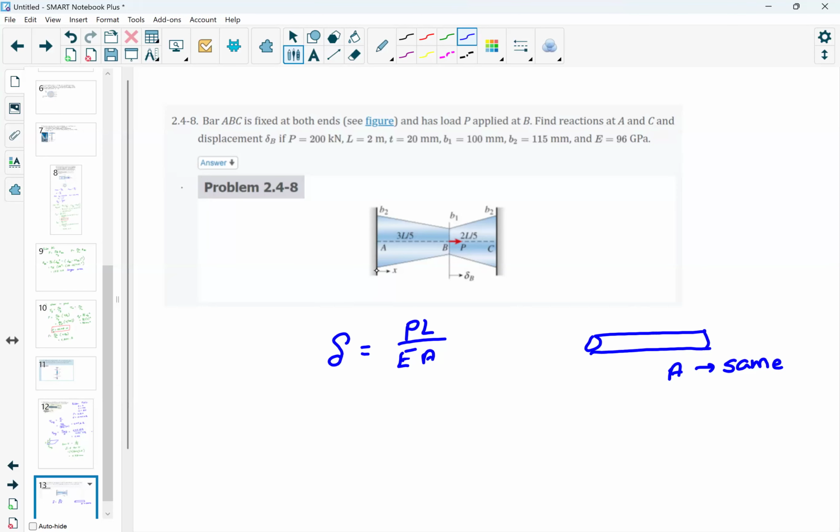So what we're going to have to do, and Tyler brought this up in class, is this was given to you in the book, the integral from 0 to L. Instead of the P, they put it in as N sub X. N sub X would mean that the force is varying with the length, dx over E A X.